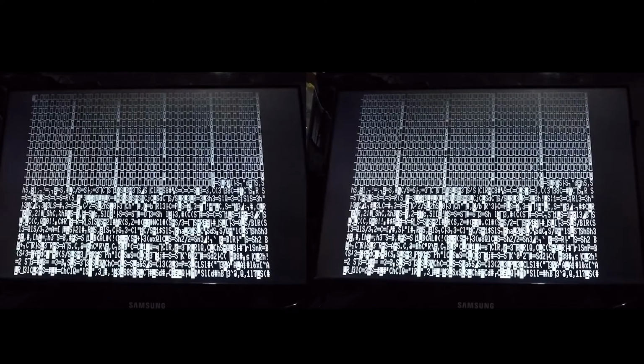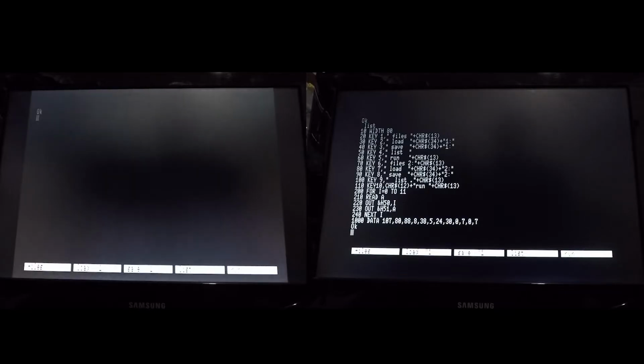So this time around, I'm looking at the Samsung LCD TV that I normally use with the Spectravideo. And on the left is the image with the standard Disk Basic. And the background is a little bit flickery and horrible. But on the right, same TV, same system, after running the little BASIC program to adjust the CRTC registers, the image is much, much better. So clearly it is a benefit for an LCD monitor. And again, like the CRT, maybe the results vary from LCD monitor to LCD monitor. I don't know. I can only go by what works on the hardware that I've got.